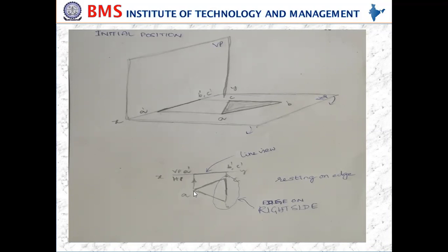So see here, I have drawn the projection. Once you draw the triangle of side, say for example 30 mm, I'm going to draw a 30 mm triangle here, 30 here, and 30 here, with 60 degrees here and 60 degrees here. I think you know how to construct an equilateral triangle. So we have constructed the equilateral triangle in the top view.